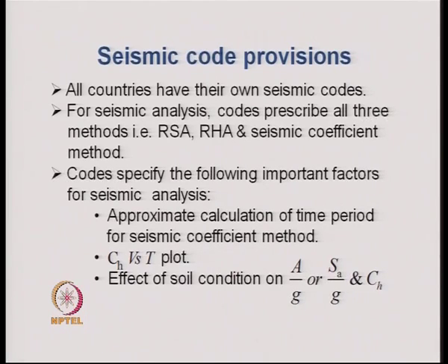That is, as the seismic waves pass from the rock bed to the surface through the soil, the properties of the soil modify the ground motions that are caused at the surface of the ground. Therefore, the spectral acceleration that we use for designing the structure should take into account the local soil effect.